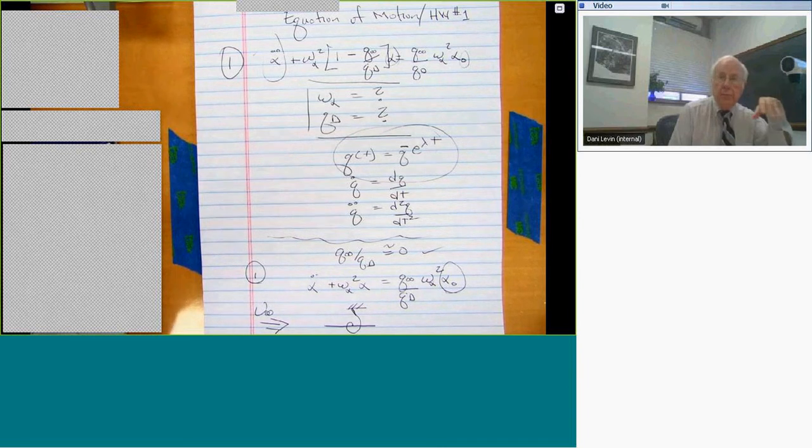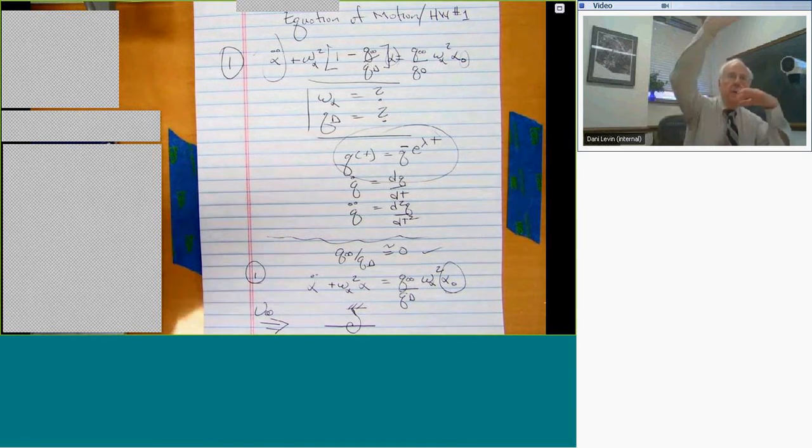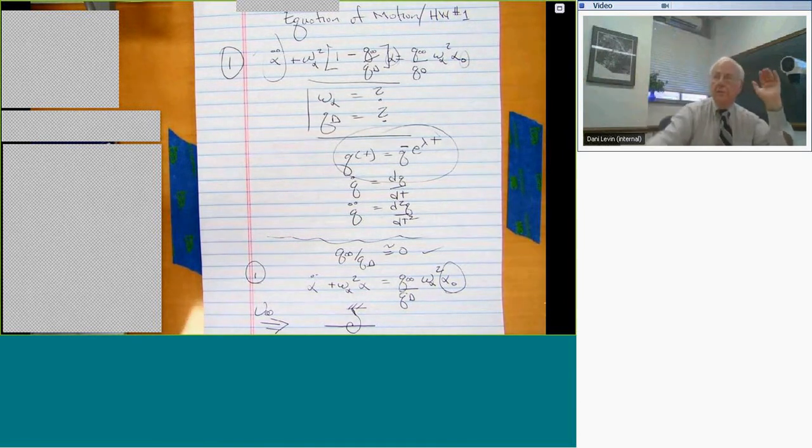Now, you realize that in this simple model, it's either going to be one or the other, but not both. But in more complex models, all the frequencies will be complex with both a real part and an imaginary part, right? And so when you do flutter analysis, at least one way you do flutter analysis, you will plot both the real and the imaginary part of the frequencies as functions of, say, flow velocity or dynamic pressure, and you'll see what happens at certain magic values of flow velocity.